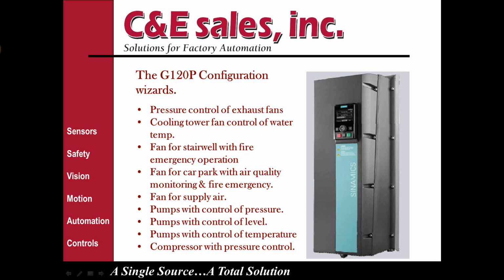They have fans for control of the air quality in stairwells and also in car parks, with the added feature of fire emergency operation. So you can have a normal operation, and then you can also have a forced operation for fire emergencies. You can do fans for supplying air for HVAC. There's a wizard to control that. Wizards for pump control of pressure, control of level, control of temperature, and then for compressor pressure control. All handy wizards that you can go through with Starter or with the Intelligent Operator Panel to configure the drive for those applications.